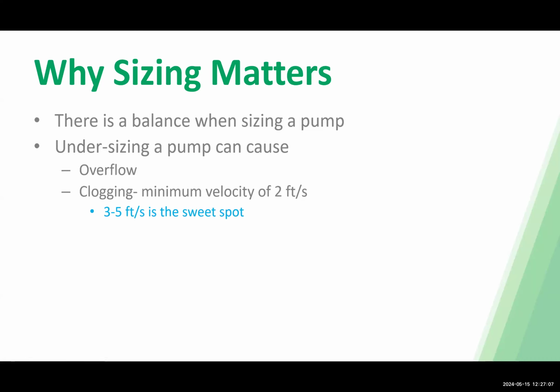The main reason why we recommend that is because products nowadays have gotten to be a lot more water conservative. So specifically toilets, just to keep that in mind, toilets in recent years have dropped in the amount of water that is used when flushing, which means that you have the same amount of solids that are going into your basin, but you have less water going in there as well. So you need to keep the lesser amount of water moving faster to keep those solids moving. So that's why we recommend 3 to 5 feet per second, just to make sure that there's not any kind